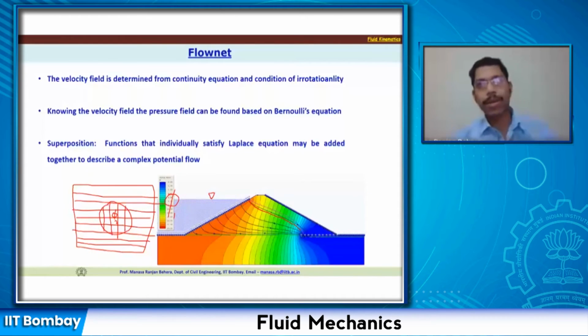These are very critical. Okay, so these are the lines that we can plot typically, which show you the streamlines or flow lines. And you see here, these are the lines which are going perpendicular to the streamlines. This shows you the equipotential lines. Okay, so you can find out the characteristic and how the flow net looks like. And what is the advantage here? If you look at this streamline, the spacing is quite larger or spacious at this location. But as they flow and come towards this, the spacing is less. So what does it mean?